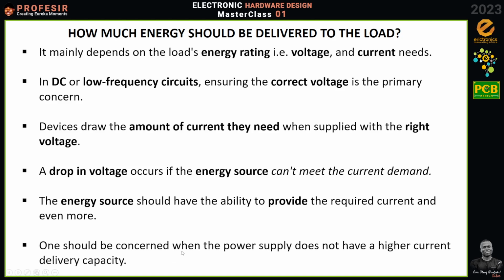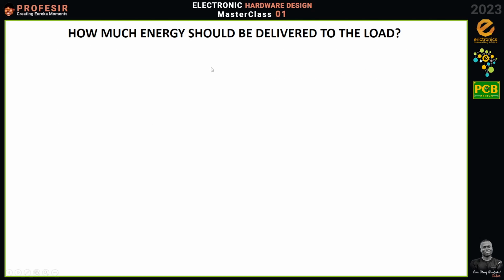So, like I said, when you connect systems, you should rather have a system that has a higher current carrying capacity. Your power source should be able to deliver a higher current capacity, okay? But for the voltage, you should always make sure that the voltage is matched. Now, later in the next sessions, I would explain why this is the situation. Is that okay? Okay.